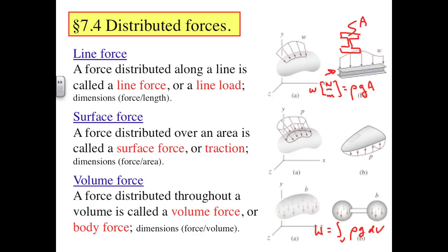In many cases, the line load is just a constant, because beams often have uniform cross-sectional area. In some problems, you may see a step increase or decrease in line load along a beam corresponding to a changing distributed load beyond the self-weight of the beam. It is also possible that the line load could be a function of position along the beam.